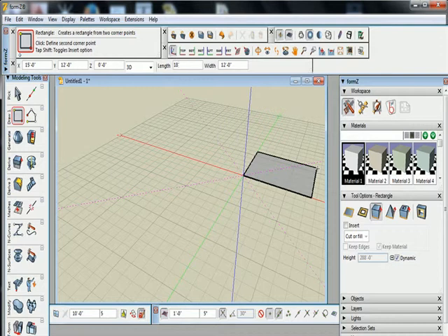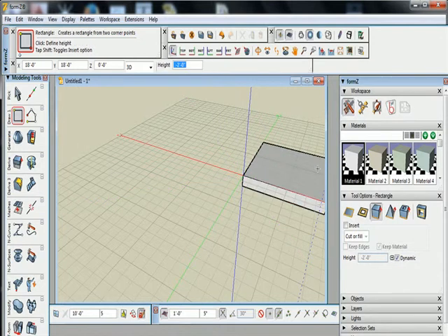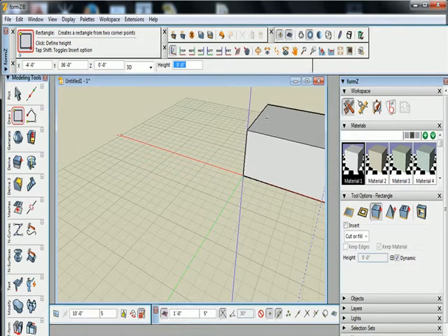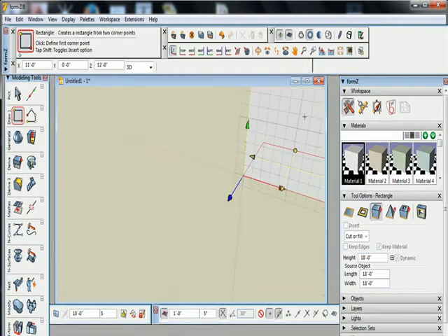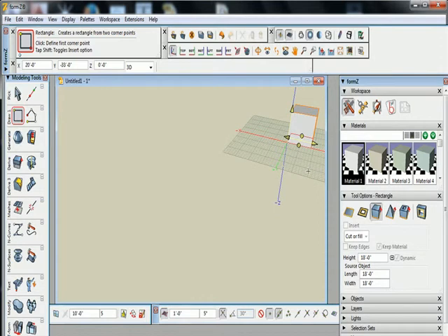18 foot length. When you want to input the width, hit the tab key, and that tab key will move you over onto the width column, and in the width column type again 18 feet. Enter. And then that area changes from length to width to a height. Notice that? You could go for negative width, or negative height, or positive height. And in that, again, if you let go of the mouse and type in 18 feet, you got yourself a cube that is 18 feet.